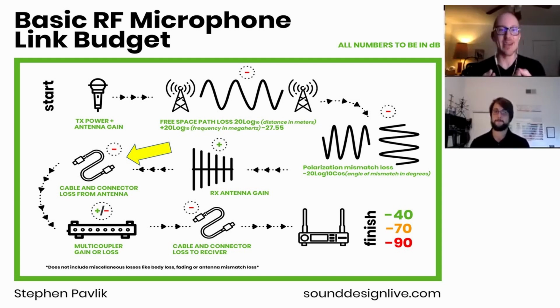How significant is that? I guess I could also look at the specification sheet for that connector? Yes, and so cables and the connectors do break down over time. So you can look at the specification sheet for whatever connector you have. Good connectors should be either no loss or about 0.5, which is what I've put in these coming up. Connectors that have broken down over time can be like 1 to 1.5. Hopefully not over that. That's pretty much a broken cable or connector. But also same with cables, where they get broken down over time, they exhibit more loss.